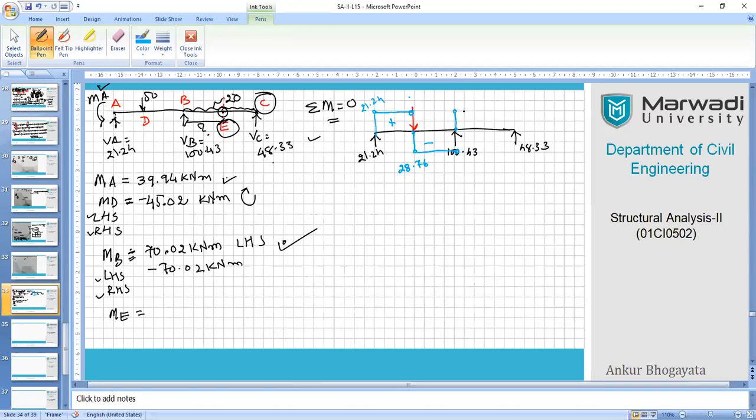So beyond this, we have to reach into the upper side because the answer will be positive definitely, and that answer will be nothing more than 71.67, right? It will be 71.67 because you have to deduct this 28.76 out of 100.43. So the answer will be positive, so we are going up, and now the UDL is there.